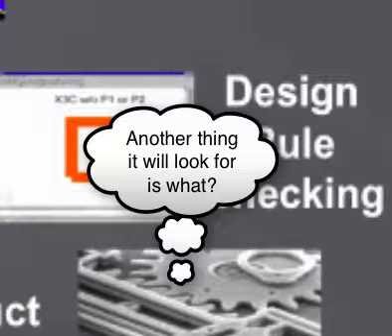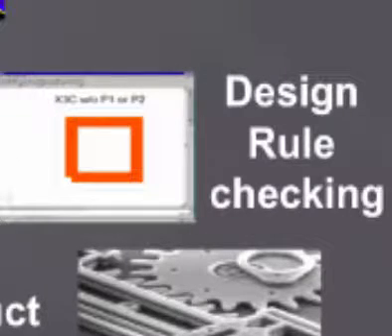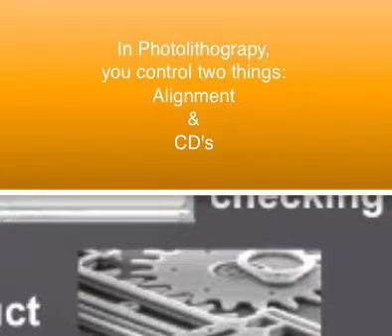You're going to align things, right? One layer you're going to align to the other. Remember when we did the backside alignment? We couldn't see half of the wafer, right? You can only see 1 mark, not 2. And remember how it ended up? They were misaligned. Half the wafer was misaligned. So alignment's the other thing. So if you say, yeah, they've got to be perfectly aligned, well, nothing's perfect.